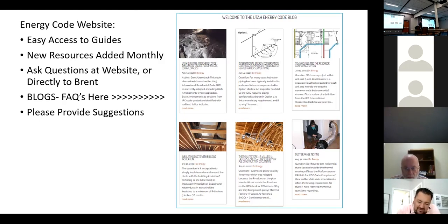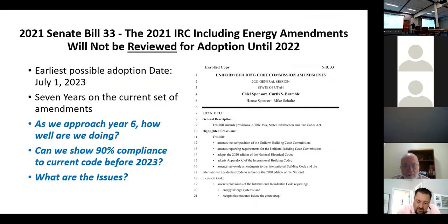Well, with that, they'd run ductwork through the whole crawl space that was not insulated. This is in a cold northern county. And so by the time the furnace at one end of the house pushed air to the other end of the house, guess what? It was cold. And so I wrote about that one. A commercial one on hot water piping, townhouses. When you do REScheck on townhouses, what's part of the thermal envelope, what isn't? And so anyway, there's a number of things in there that might answer some questions, YouTube videos.